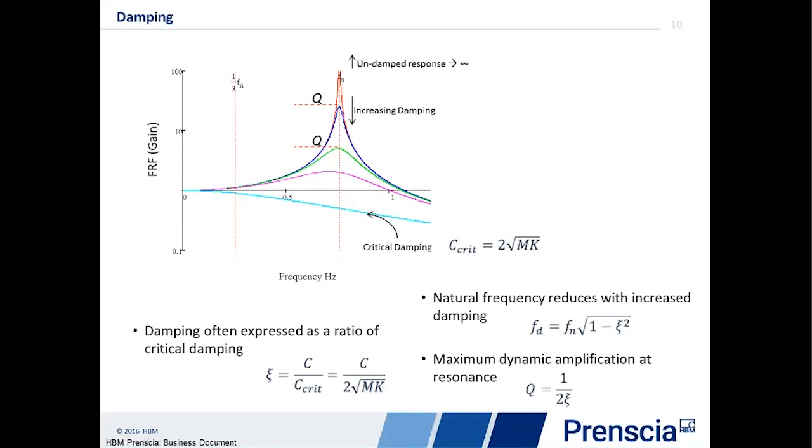So basically, we've got this means of calculating this metric, the damping ratio ζ, calculated as the ratio between the damping coefficient and the critical damping. And so this one goes up to 1 when we hit the critical damping, and when we're very lightly damped, it goes down to 0. So that's typically between 0 and 1, so 0% and 100%.